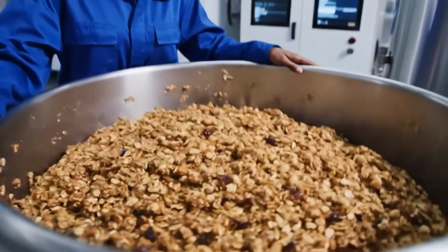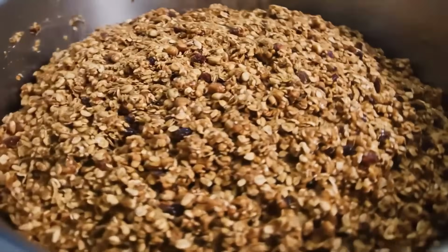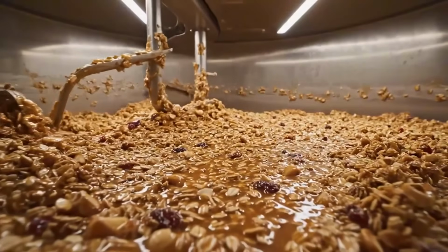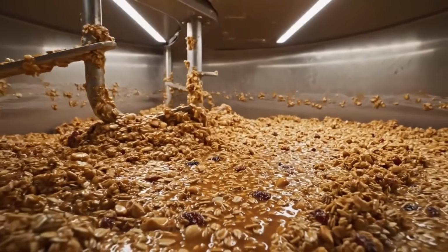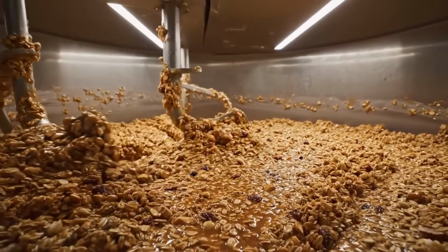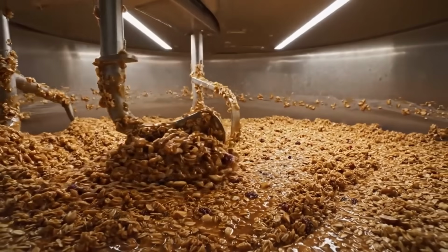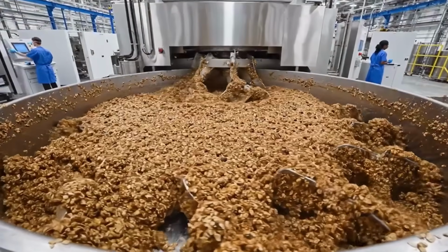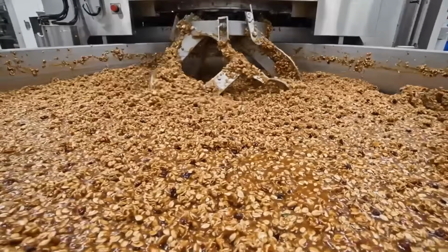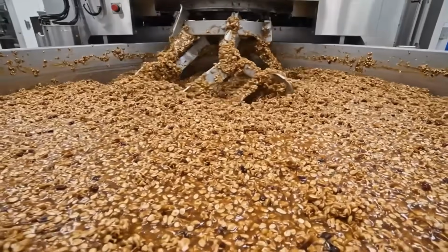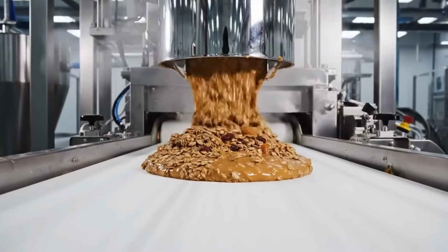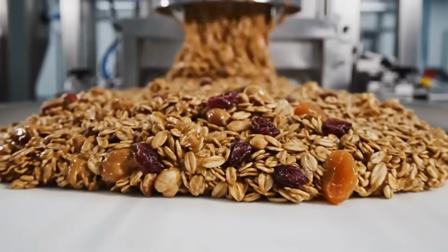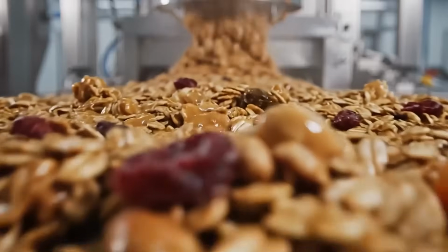Once mixed, the mass is transferred to a forming system that creates a continuous slab. Transfer chutes are designed to reduce segregation because heavier inclusions can settle. Many lines use a short transfer distance and a low drop height. The mass is fed onto a moving belt through a spreader that distributes it to full width. The spreader uses leveling bars and rotating paddles to create an even bed height.